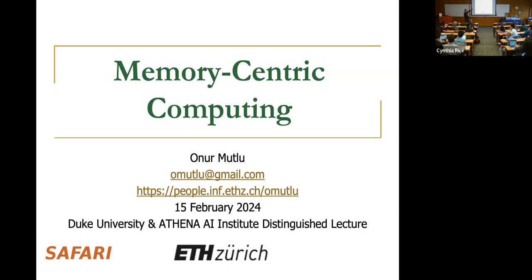So if you look at the picture that I showed you, the brain, the connectivity over there is huge compared to what we have inside our DRAM chip today, right? So that may be another challenge about memory-centric computing, right? So we reduce the off-chip bandwidth requirement, but we still have an on-chip high bandwidth requirement to move the data in memory. That's true, but I will argue that that's much easier to solve. Off-chip is much harder and much more energy inefficient, whereas on-chip is easier to solve. And maybe we need to invest more into that.